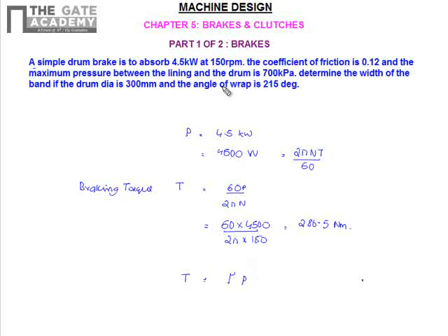Suppose this is the drum, and the contact pressure is P. The torque will be mu times the normal reaction.